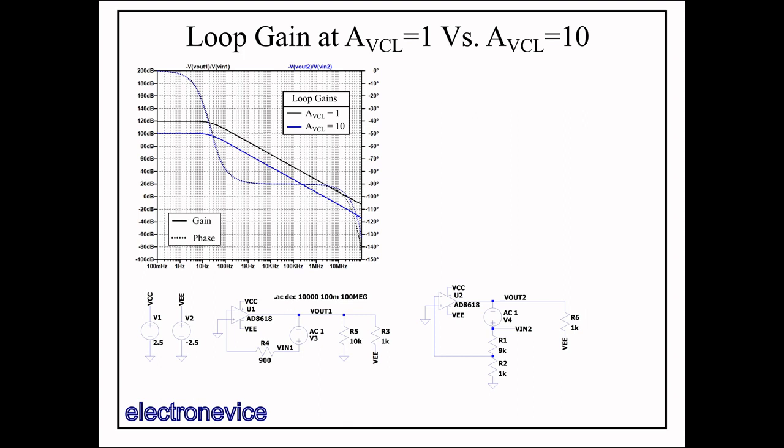Similarly, the 10K load resistance on the unity gain buffer is to match the 10K load resistance produced by the gain of 10 op-amp's gain setting resistors, and the 1K load resistors on both circuits are to ensure that the same output transistor is active, so they have more closely matched characteristics.